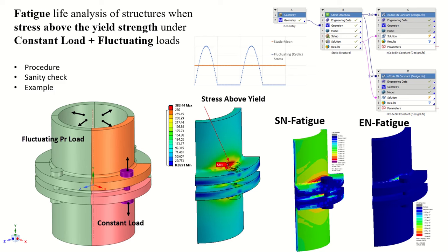When the structure is subjected to a portion of a load which is not fluctuating and some portion of a load which is fluctuating, the analysis becomes a little tricky. And moreover, when the induced stress on the structure is less than the yield limit of the material, then we can handle this using SN fatigue analysis methodology.